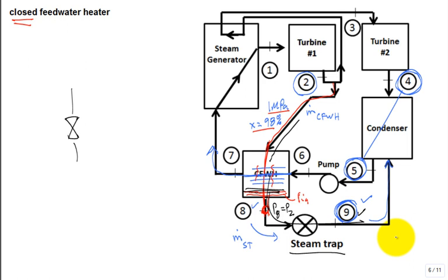You don't need electricity to operate them. You don't need all these complicated things, and they can run day and night, hopefully for a long time. But then they do malfunction every now and then, and sometimes when they malfunction, they just stick open. When they stick open, unfortunately, it's a wasteful situation in a steam power plant. So a lot of engineers and maintenance guys go around and double check steam traps to make sure they're functioning right. So the steam trap is hopefully easy to understand, right?